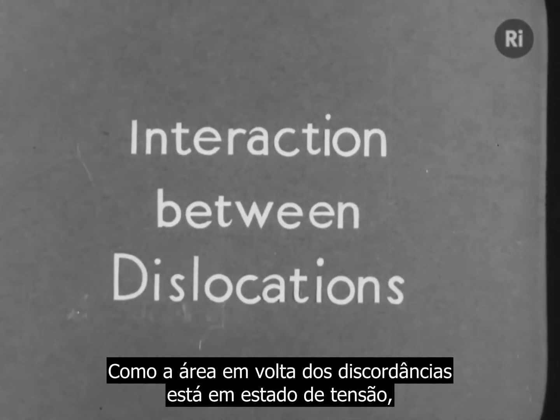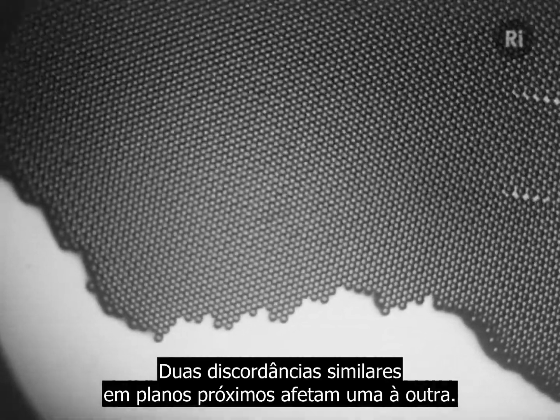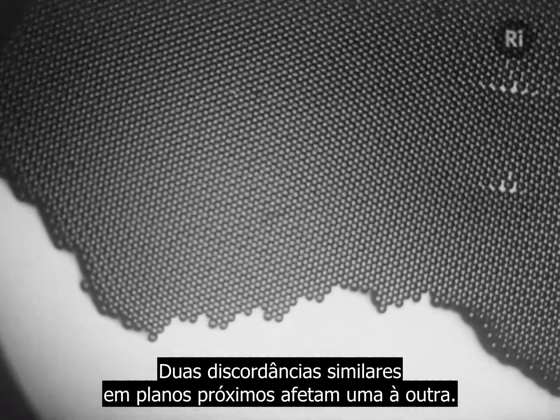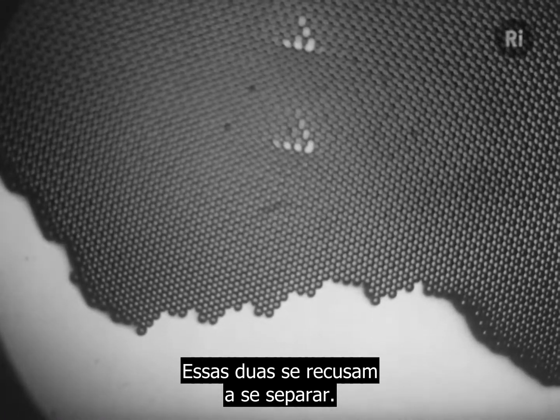Since the region around a dislocation is in a state of strain, there are forces between neighboring dislocations. First, we shall see two dislocations in relative positions of equilibrium. If one is displaced, it returns to position. Two similar dislocations on neighboring planes attract one another. These two refuse to part company.